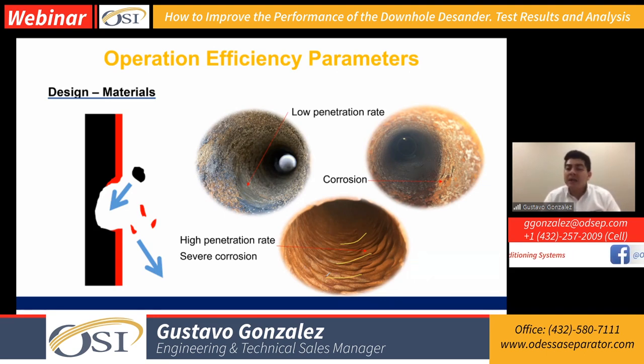That's why it's so critical to size everything appropriately, and that's the main topic here. Desanders, as we mentioned at the beginning, are one of the most common options due to price and simplicity, but at the same time there is a science behind how to choose the right helix based on the flow rate that you're handling and the type of particles that you're producing.